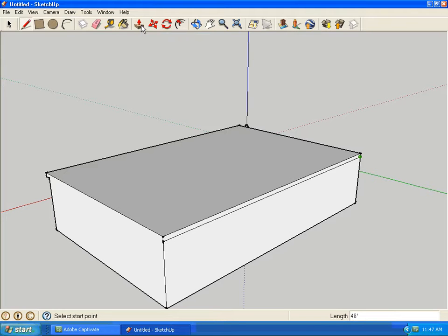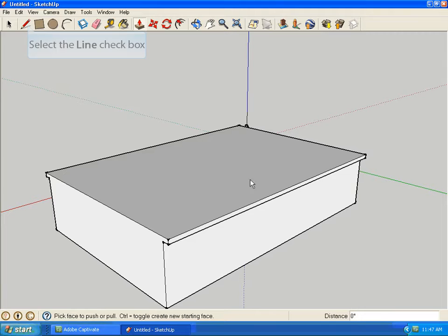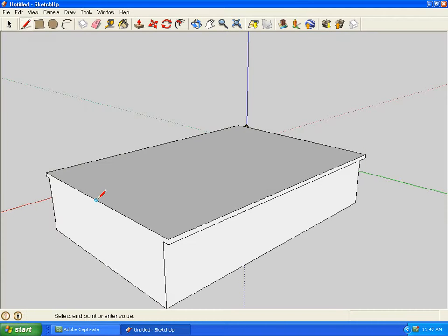SketchUp remembers measurements and is assuming that you would like to draw a line parallel to the one you made on the front side of the house. This is a correct assumption, so click on the red dot. Click on it once again and draw a red line across the rear face of the prism until it reaches the opposite edge. Once again, a red dot appears along with a flyout saying On Edge. Click on that dot. As before, click on the Push-Pull icon in the toolbox and draw the cursor down to within the newly drawn eave. Click twice. Again, SketchUp has remembered a previous command and automatically extrudes the eave 12 inches.